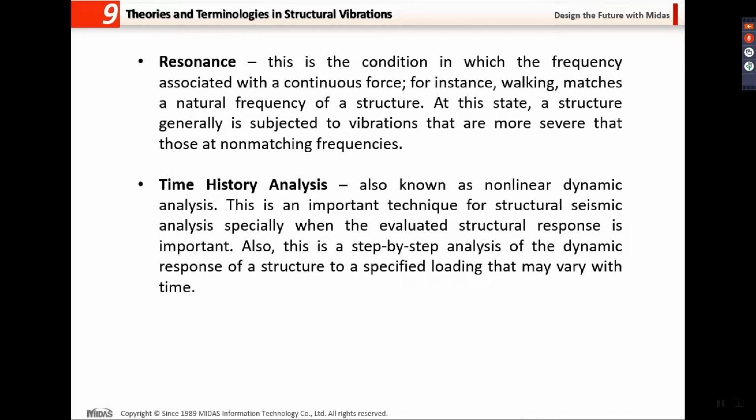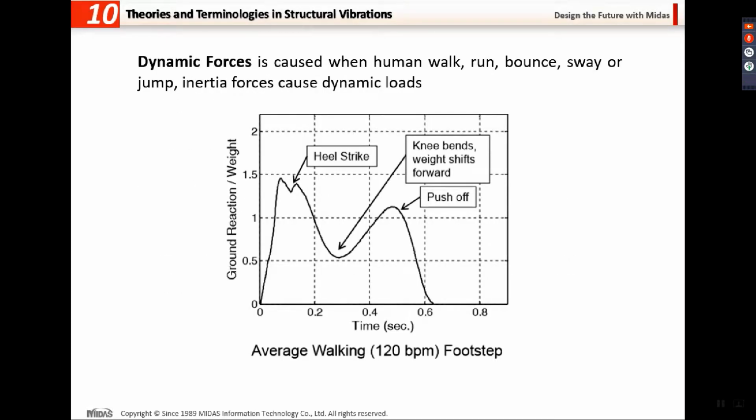Time history analysis is the analysis step that we are doing for today. It is also known as nonlinear dynamic analysis. It is an important technique for structural seismic analysis, especially when the evaluated structural response is important. Also, this is a step-by-step analysis of the dynamic response of a structure to a specified loading that may vary with time. These dynamic forces are caused, for example, when a human walks, runs, bounces, sways, or jumps. Inertia forces cause dynamic loads.